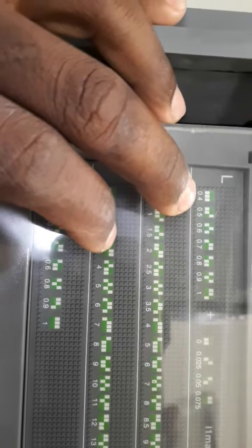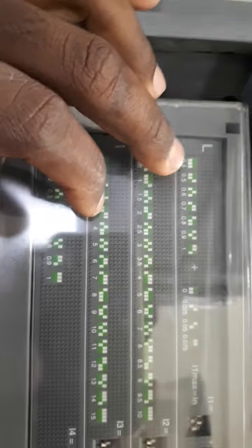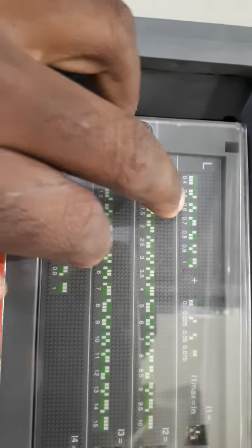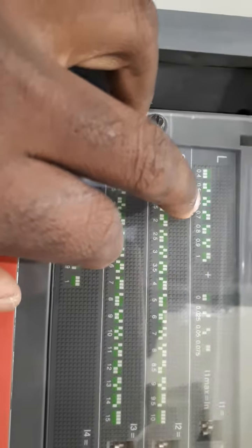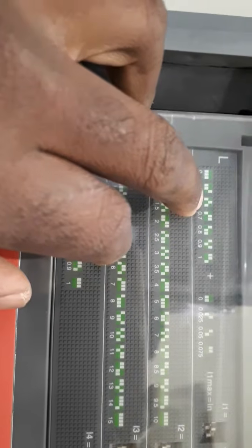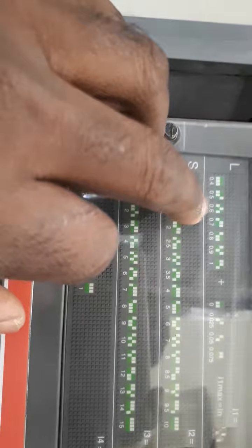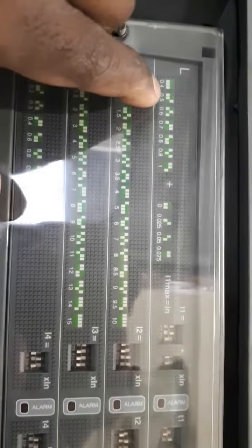Okay, so here you look, all three knobs are downside. It means the IR value, the continuous current rated amps. If the load amps taken is more than this setting value, the breaker is automatically tripped. This is the overload. So this one is 0.4. If two knobs are downside and one knob is upper side, it means the set value is 0.5. If the first knob is lower position, the second knob is upper position, the third knob is lower position, it means the set value is 0.6. So how the overload current we will set here, you look here, this is the IR value.